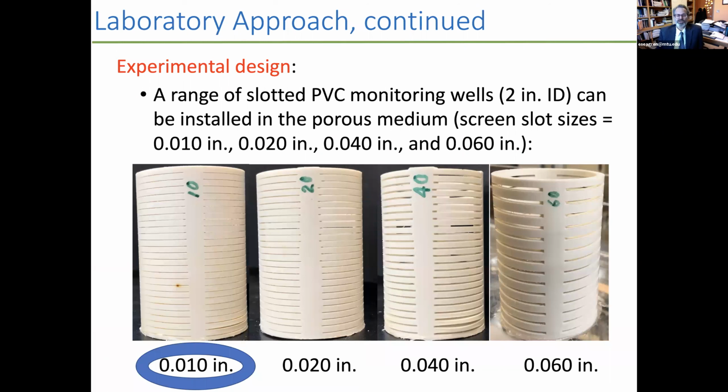And then to simulate, say we're reusing PVC monitoring wells as our unpumped wells to release amendment into the groundwater, we used a series of PVC monitoring wells with different slot sizes.